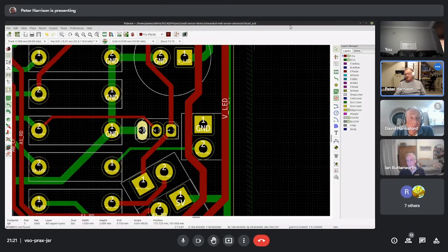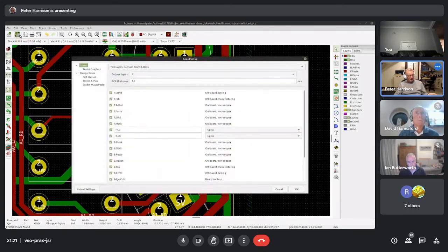No, the thing is, the three places that I go and look, generally speaking, are OshPark, PCBWay, and JLC PCB. And because I don't like dealing with PCBWay, I don't really use them much. The only reason I don't like dealing with them is they're kind of at you all the time to do stuff. So it's JLC PCB, and the JLC PCB site has all of the rules in, and you can put them in here. And there's a little button there for board setup.